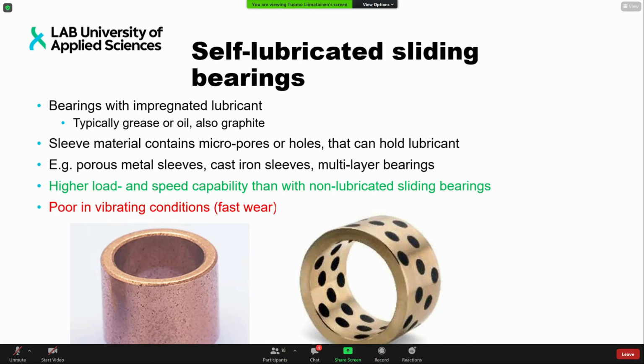Yeah. Okay, then the kulutusholkki stands for a wear out sleeve. If I don't know what the application is, I can't say if it's performing the function of a sliding bearing or not. It could be just for the reason of providing a surface, for example, for the seal to touch, so that if the seal over time makes a groove, it would make the groove into this kulutusholkki and not into the shaft itself.